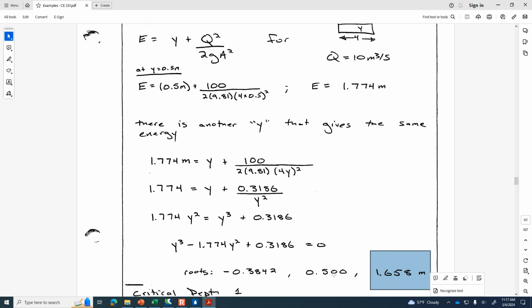And it's important to be able to not only solve this cubic equation, but then also know which root to pick. So in non-uniform flow, when we analyze the water's reaction to some sort of a disturbance, we'll solve cubic equations a lot. You're going to probably solve 20 or 30 of them this semester. So this is number 1 out of 30. Then once you solve the cubic equation, you have to pick the right root. And oftentimes you'll know which root to pick because you will have analyzed conditions prior to the disturbance upstream. Was it supercritical or subcritical? And then that'll guide you most of the time on which root to select.